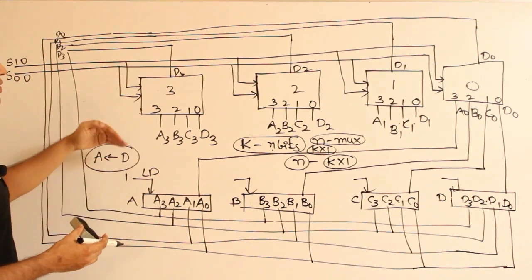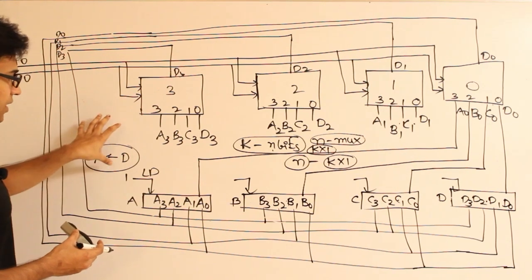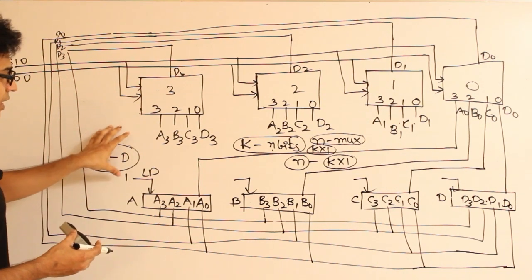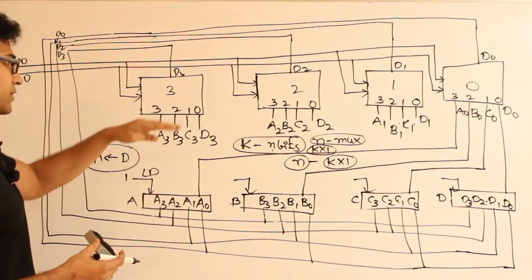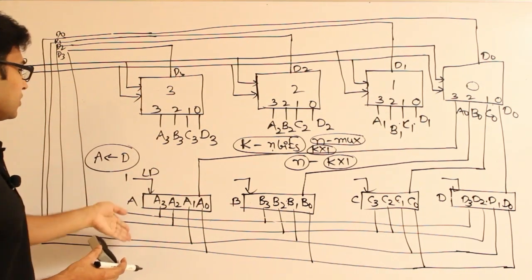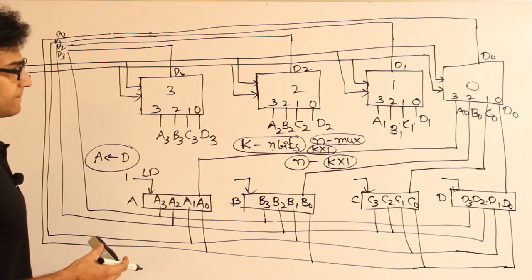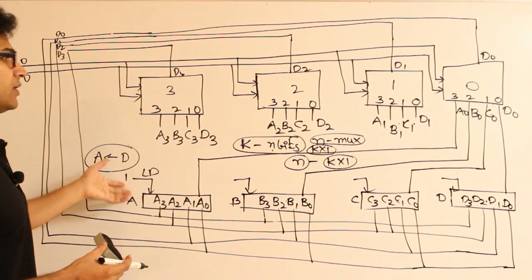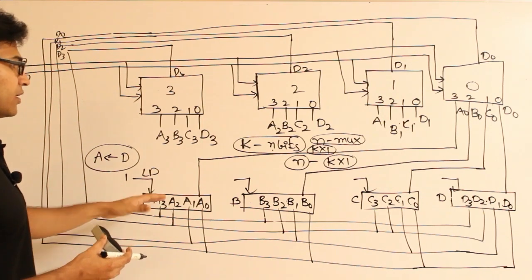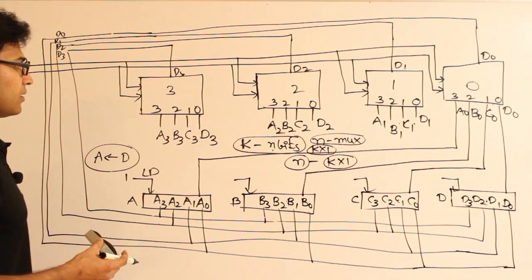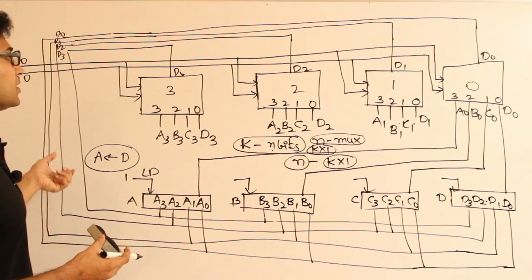And similarly we can have the memory unit, right? For that memory unit also, the output of the memory unit will be connected to the multiplexers, and the input to the memory unit will be from the bus. Got it? So that is how all the units we have can communicate using this bus, right? In general we'll have a 16-bit bus.